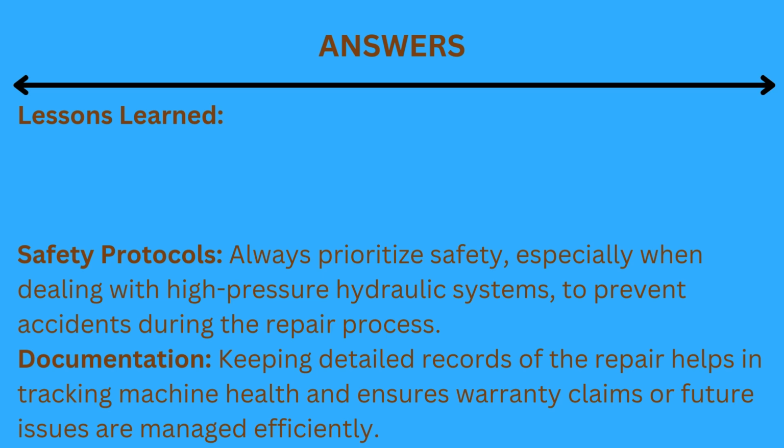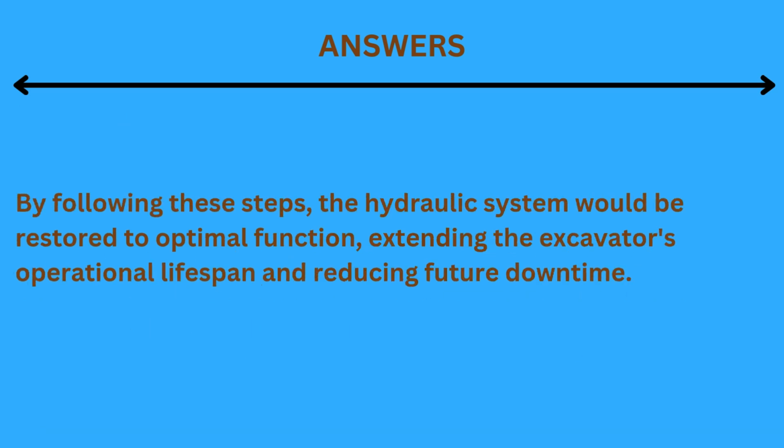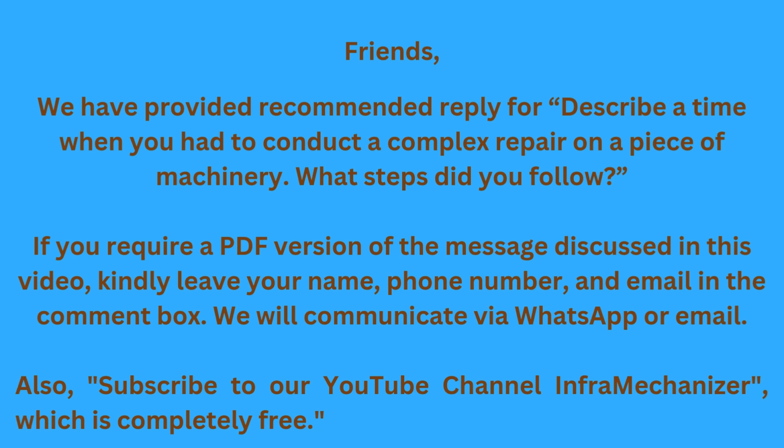Documentation. Keeping detailed records of the repair helps in tracking machine health and ensures warranty claims or future issues are managed efficiently. By following these steps, the hydraulic system would be restored to optimal function, extending the excavator's operational lifespan and reducing future downtime. Friends, we have provided recommended reply 4.